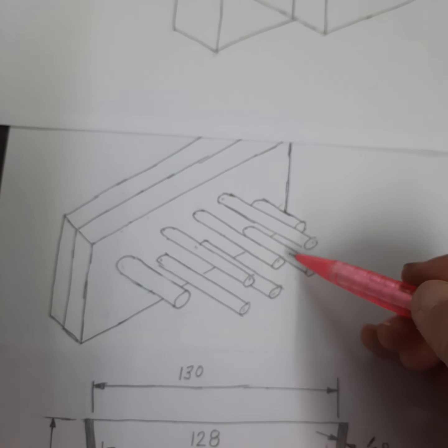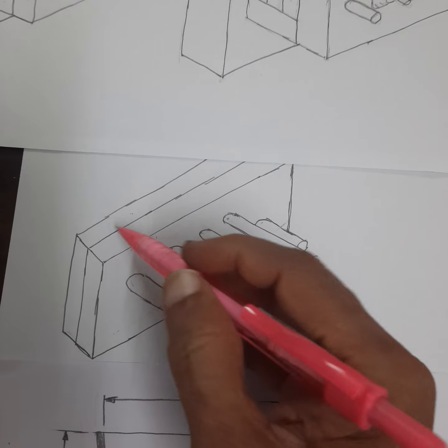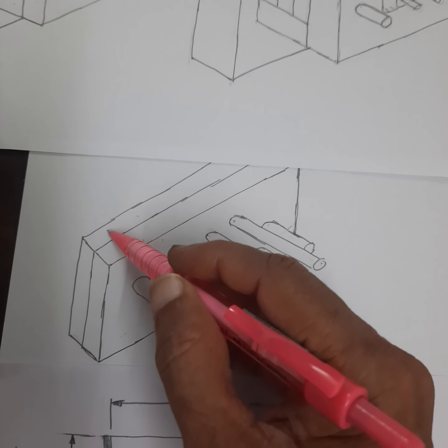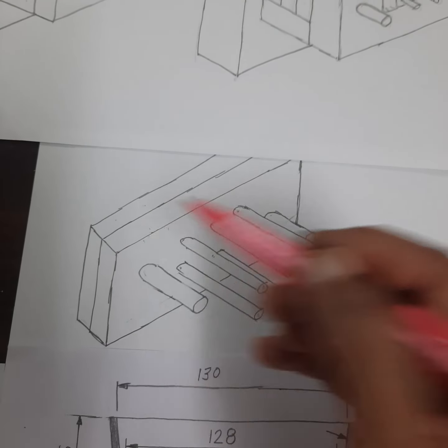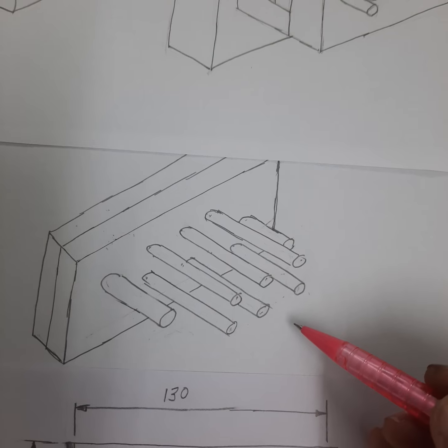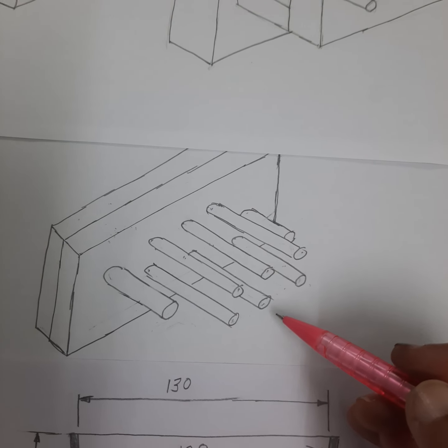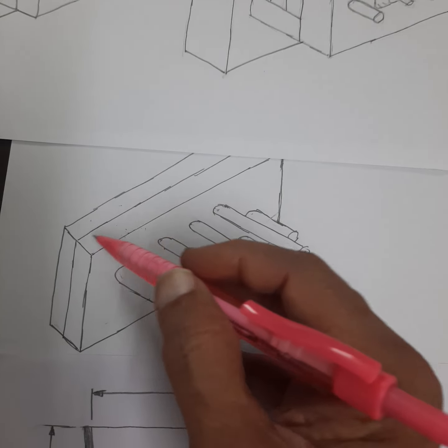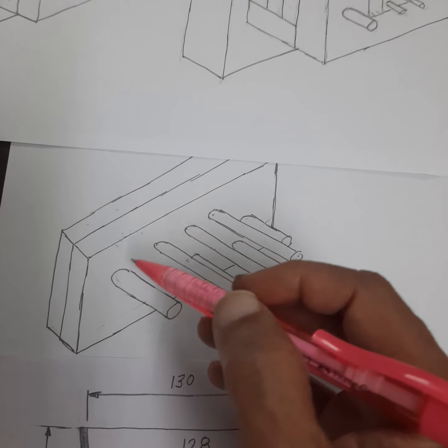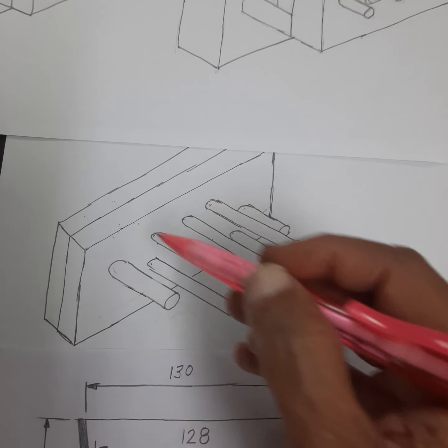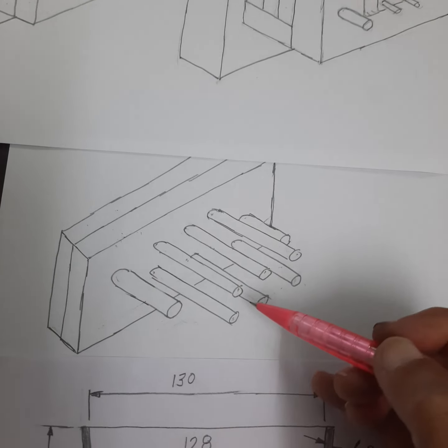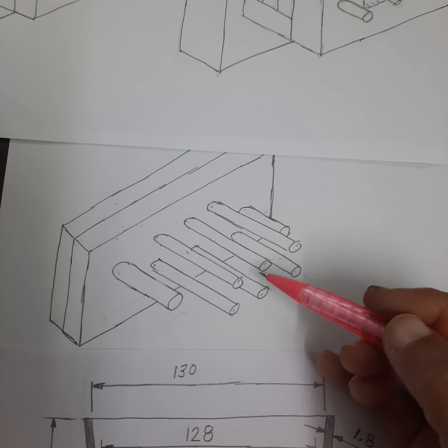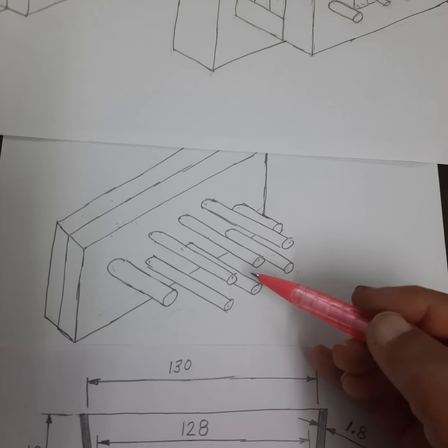Once all the 8 pins are fitted, it is closed with another plate called the ejector plate. Both are fastened together. So this is the assembled view of the ejector mechanism used in this design. These 2 plates are fastened together, and as a result all the elements will be moving in and out for the purpose of ejecting the component out of the core during the ejection cycle.